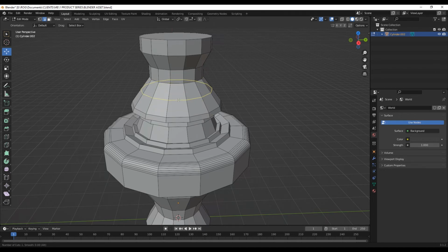So after selecting the number of cuts you want to make, for me I want to make 1. If you left click again, now your cut has still not been made. It's time for us to place this cut where we want to place it. Now I'm not clicking my mouse, I just left click once, and now I'm just dragging around this mesh here. So I can place this cut here by left clicking. Then now that is placed. So you can keep doing this.